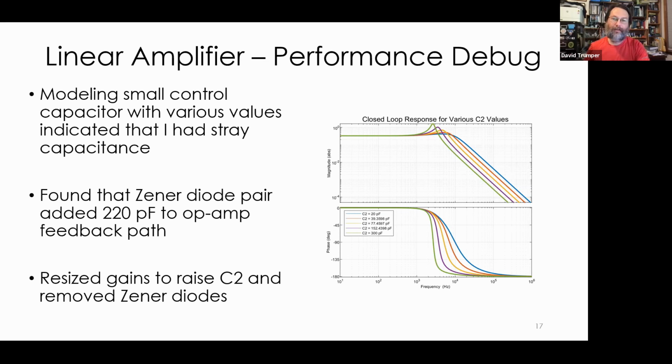And then getting rid of the anti-windup is not that big a deal because you saturate at plus or minus 10 or 12 volts anyway. It's not like floating point words where you can go off to infinity. Analog circuits stop at some level anyhow. So getting rid of those anti-windup diodes didn't matter that much.